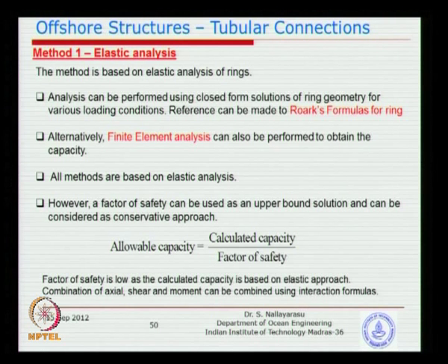So the allowable capacity is calculated as the calculated capacity divided by a factor of safety. Even though we do elastic analysis, when you do elastic analysis you might think you do not need to divide by a factor of safety, because it is within the elastic limits. But elastic means you can go up to yielding. So that means you definitely need a factor of safety to be defined.